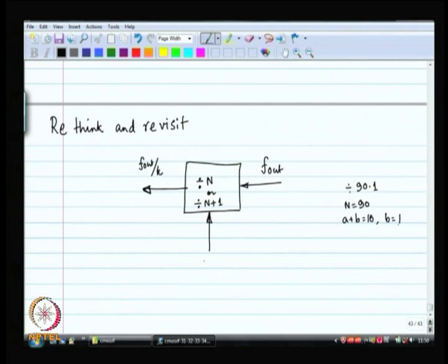Right. This was how we managed to divide by 90.1. So, f out will be 90.1 times the reference frequency. Reference frequency is 10 megahertz. So, f out will be 901 megahertz. This was the strategy that we had.